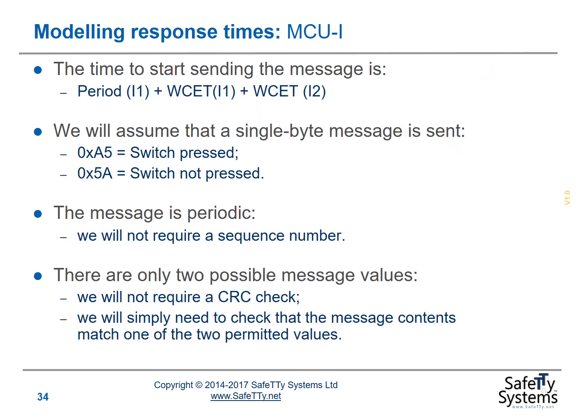So using the techniques that we've worked with previously, we can say that the time taken to start sending the message is period I1 plus the worst case execution time of I1 plus the worst case execution time of I2.